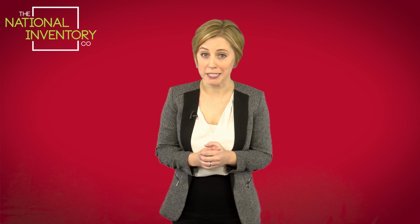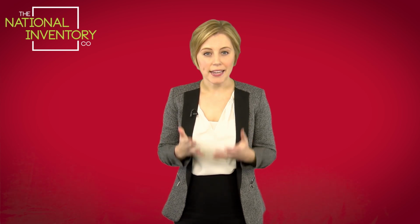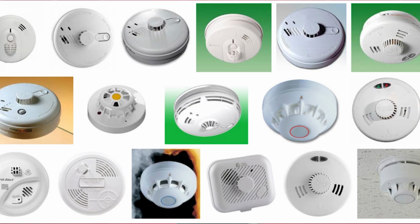Heat alarms. Heat alarms are traditionally found within the kitchen environment, as a smoke alarm wouldn't be suitable as it would trigger every time you burn a piece of toast, whereas a heat alarm only triggers under excessive heat.